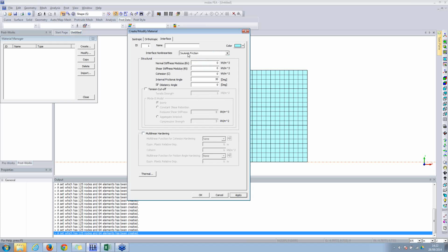This is a basic interface material, very commonly used for checking slip between a steel beam in a steel infill type of beam which is surrounded by a concrete pour. Also for interface behavior between shear studs in composite section and the surrounding concrete slab.